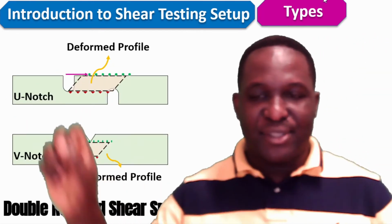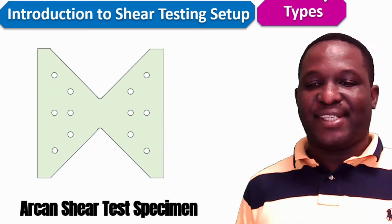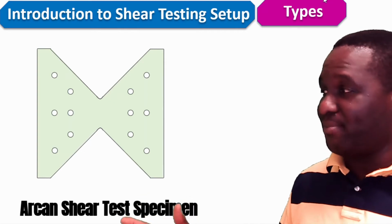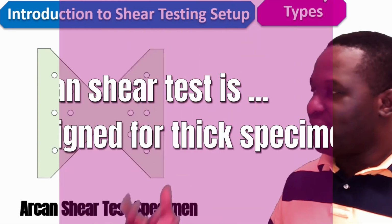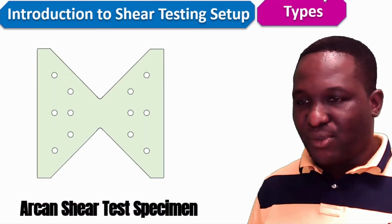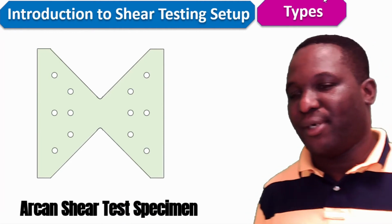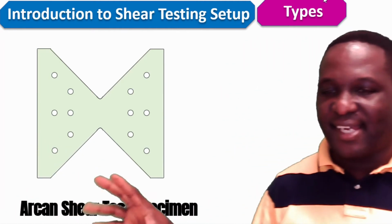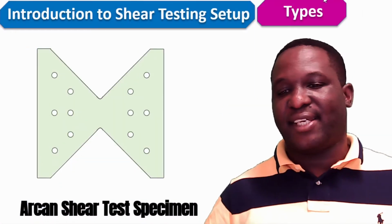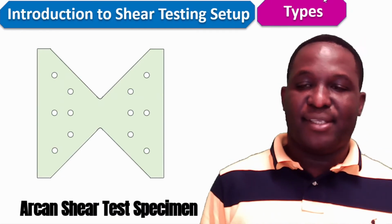But we're not talking about these two types of specimen in this video. Let's look at what we are really interested in, which is the Arcan shear test specimen. I'm really interested in it because it's designed for thick specimens, and you can do a whole lot of interesting things from your shear test setup, and I'll talk a little bit more about that later on. This is a classic design. Some people call it a butterfly specimen because the shape looks like that of a butterfly, and that's what the Arcan shear test specimen looks like.